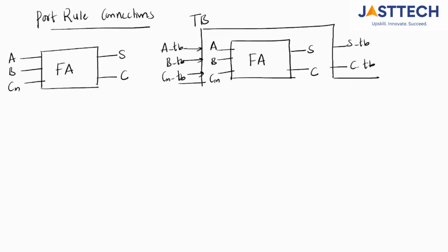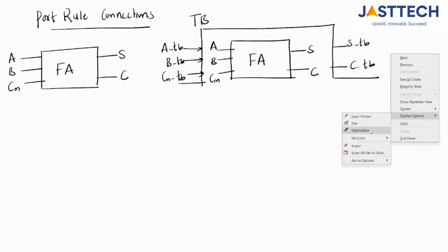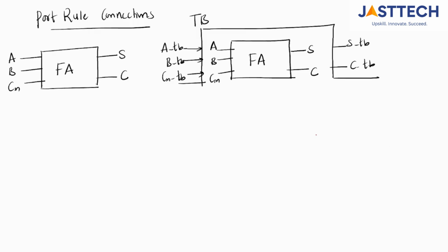For the design, the inputs should be net data type, and for the test bench inputs, it can be reg data type or net data type.